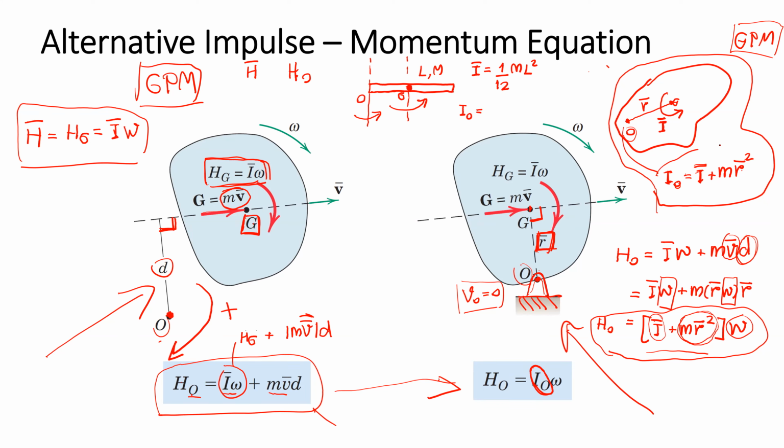By applying this relationship, if you want to obtain the moment of inertia at the left end of the bar instead of the CG of the bar, you're gonna have the I bar first plus the mass and this offset squared.